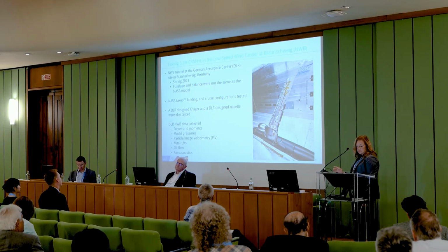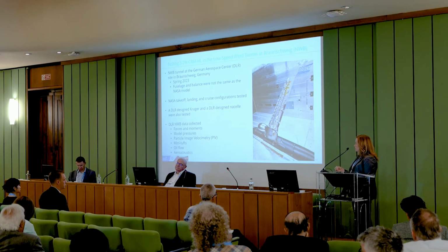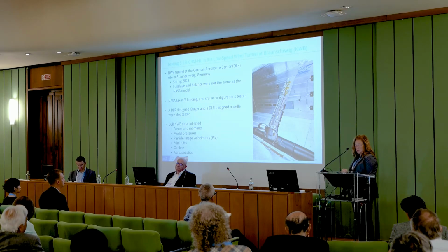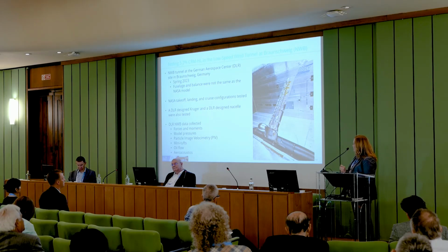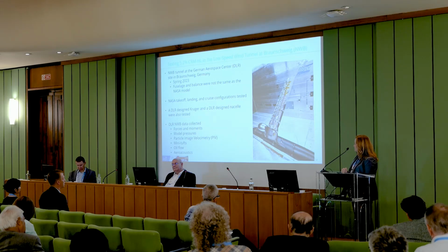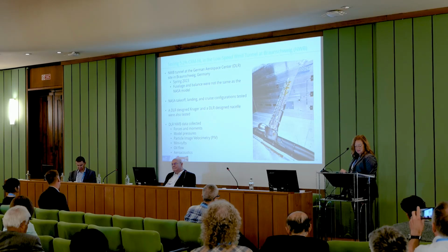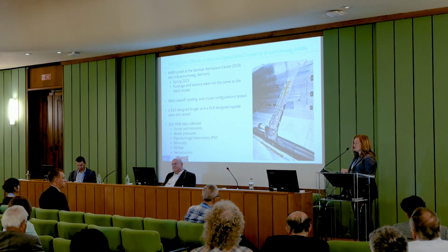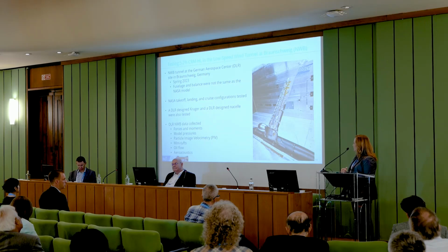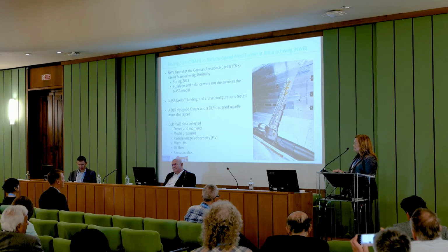Okay, so at this test, DLR was able to test all three configurations, the takeoff, landing, and cruise. DLR also tested a Kruger and a nacelle that they designed, and lots of data was collected. Ralf will give more information about that next. But forces and moments, model pressures, PIV was done, mini tubs, oil flow, and aeroacoustic data was obtained during that test.